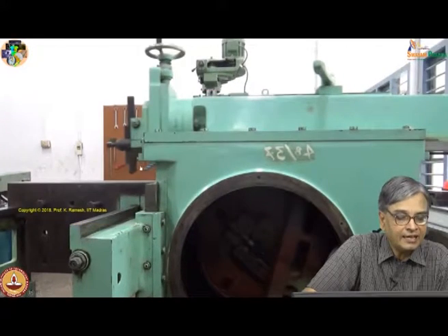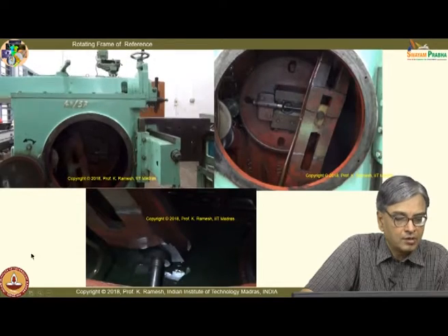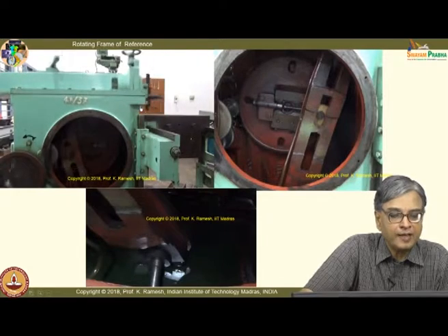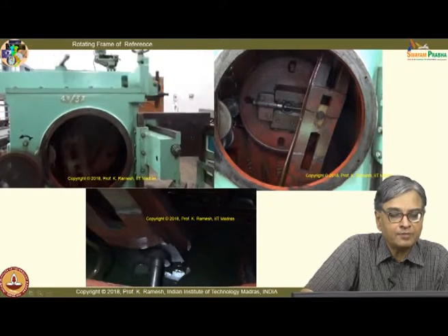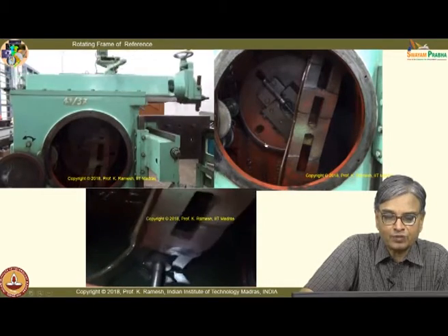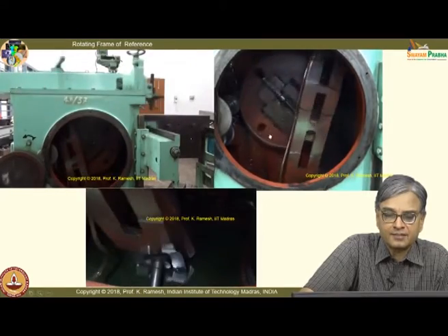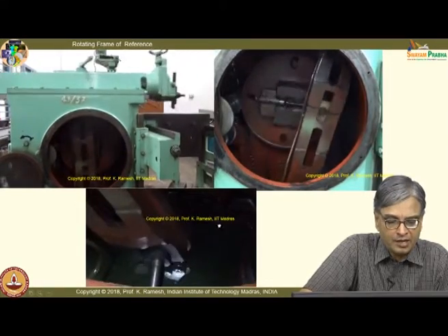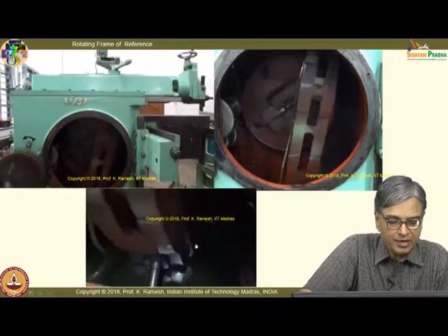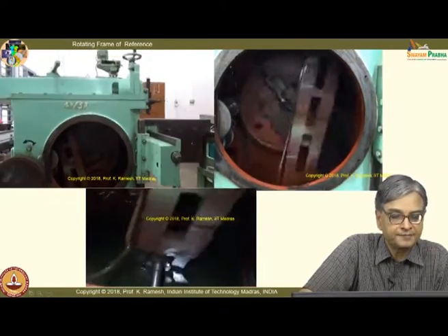While cutting the specimen, it goes slowly, when it comes out it is fast, and this is the mechanism that we are going to analyze. I also said lubrication is very, very important, and it actually works in a bath of lubricating oil.